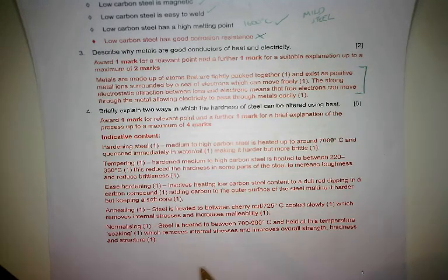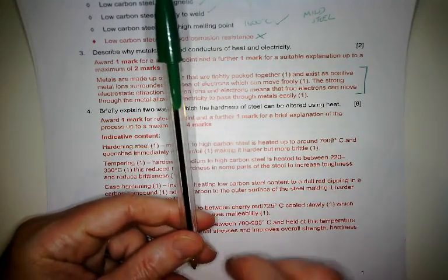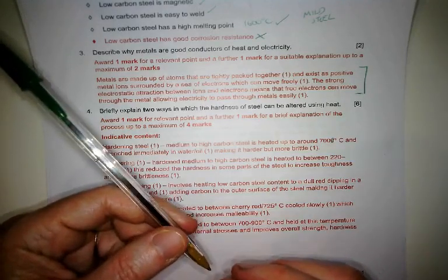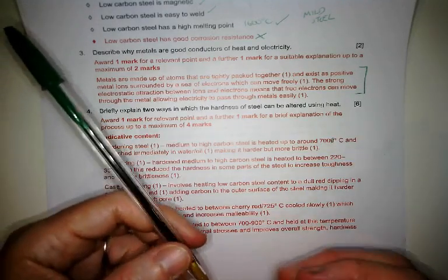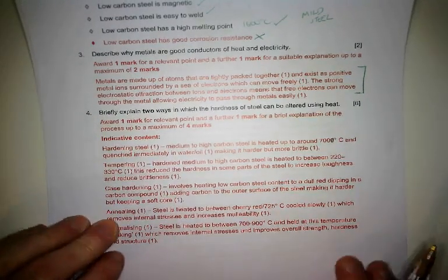Me personally, I'd talk about hardening and tempering. I know about those ones, and I can talk about those with temperatures and things like that. I could talk about case hardening. It's a nice one for things like chuck keys on the lathe, where we've got an object such as my pen. It's going to go into a hole, and the outer skin of it is going to be hardened, but the inner is left natural, so it can withstand that twisting force.